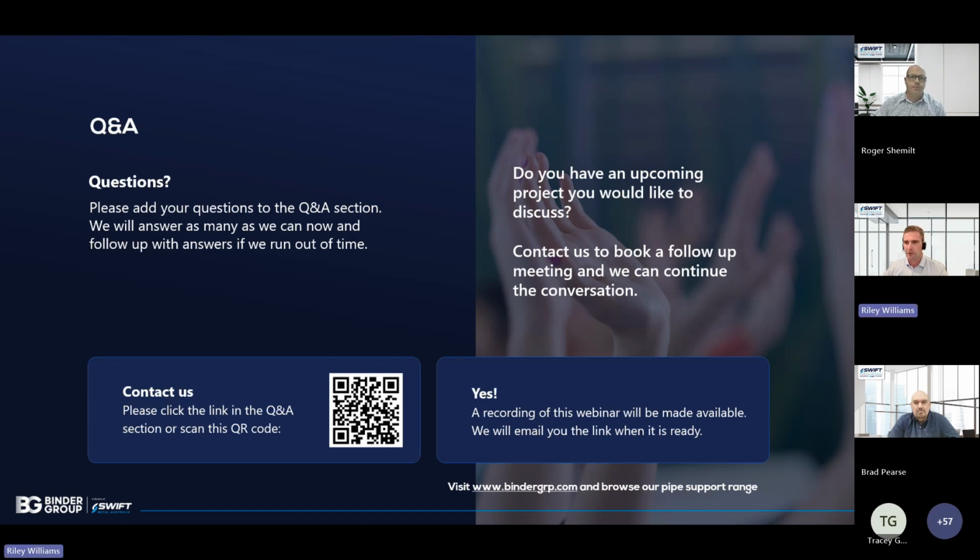Rog, we have had one come in here specifically on line stops for insulated cryogenic systems. Do you have some comments to make on that, Brad or Rog? With a line stop or an anchor, there's two parts to it. We have to anchor the support to the pipe, so there's got to be a mechanical stop inside the pipe.